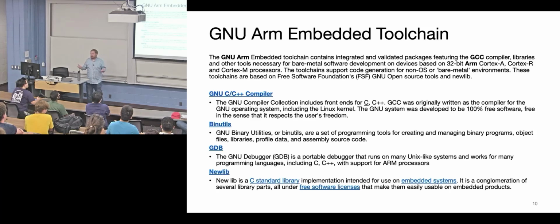And so how do you debug that? Because as soon as you put your JTAG debugger on there, or your USB cable to walk through the code, it injects power and it corrupts your signal. Now you've taken this thing that was a bug that only exists on energy harvesting and added power, and the bug goes away. And so I had a student go through and rewrite GDB to actually have breakpoints that would inject or not inject power into it.